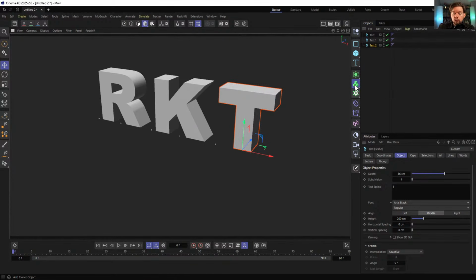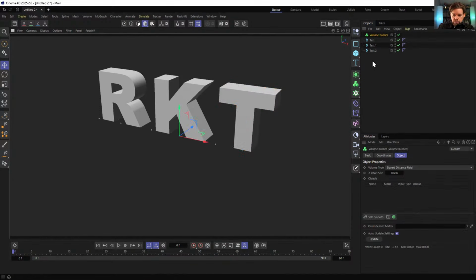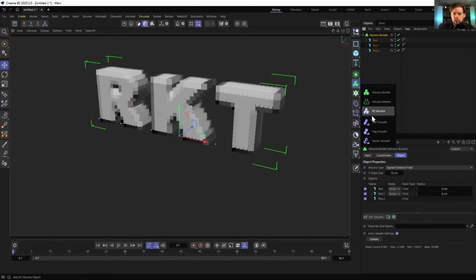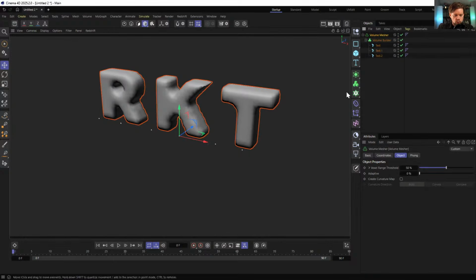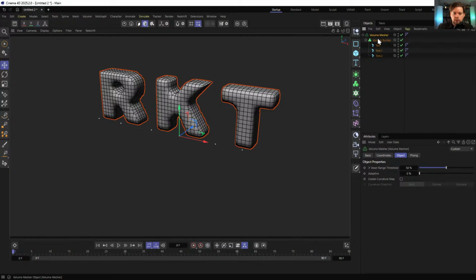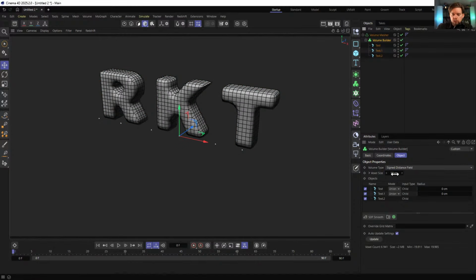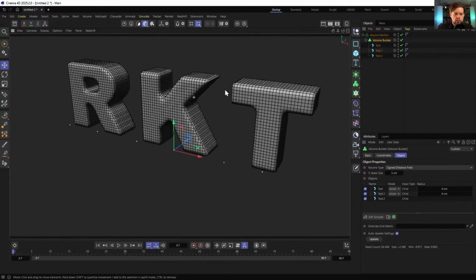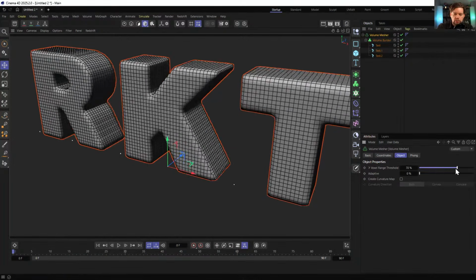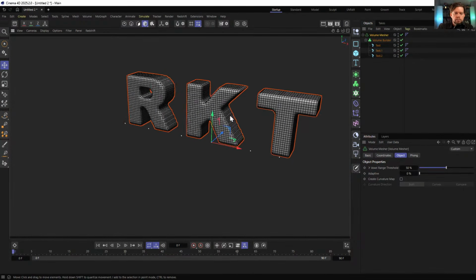If we throw this into a volume builder, drop them all in, plop it out. Now we throw that into a volume mesher, which of course is going to merge them into a single mesh. If I make this editable, it's one object. It doesn't explode them out as separate objects. So, of course, we can make all the standard changes, increase the resolution if we want to, and we can inflate or deflate by dragging our voxel range slider.